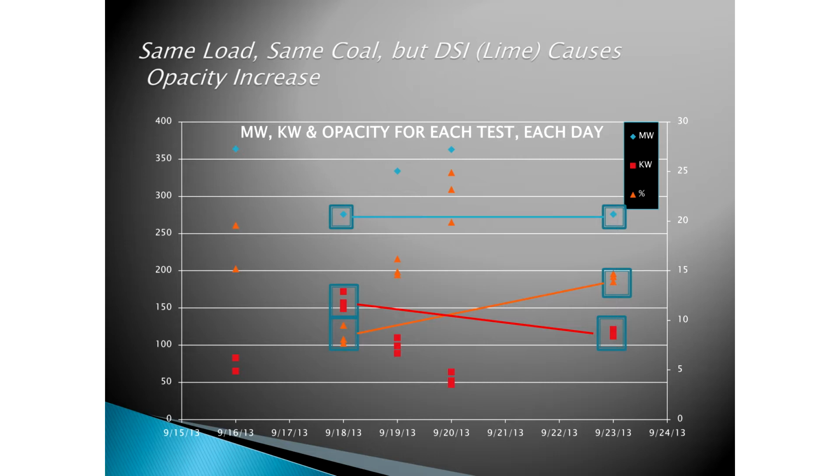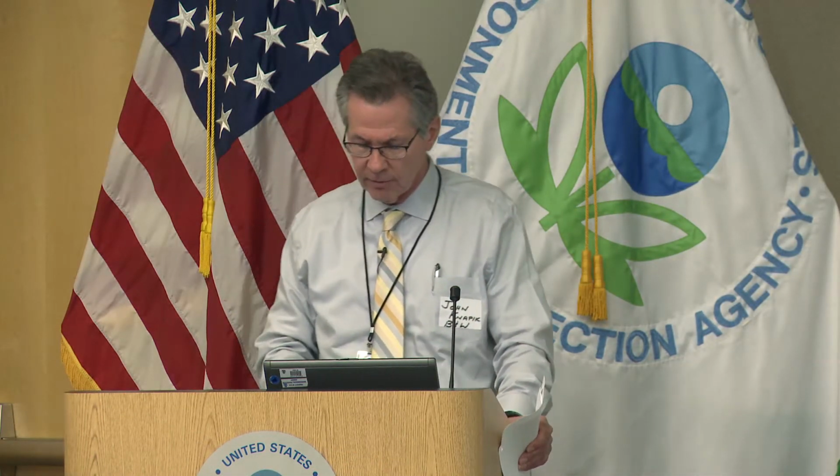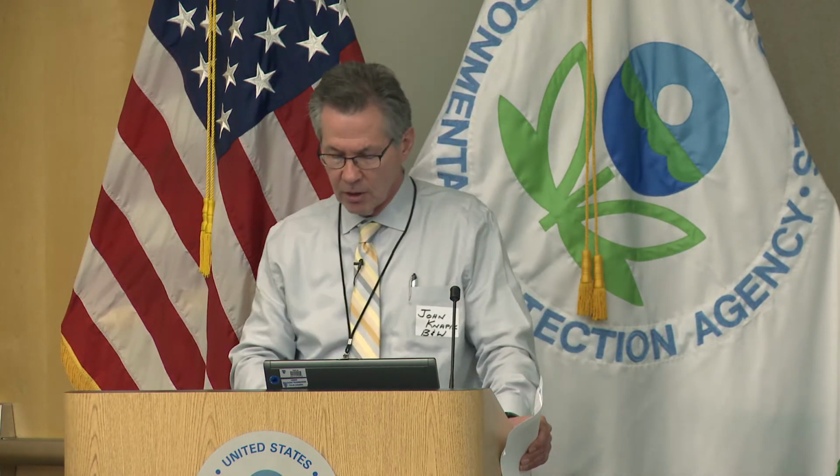What about other sorbents? In general, sodium compounds would keep the resistivity the same and might even enhance it a little bit. So you might not see this phenomenon there. So chemistry affects the resistivity of dust. The resistivity of the dust affects the total power in the precipitator. Each field operates differently, and voltage controls are the brain. They've got two things to do: control the sparking and push the transformer to its limits. Are there any questions?